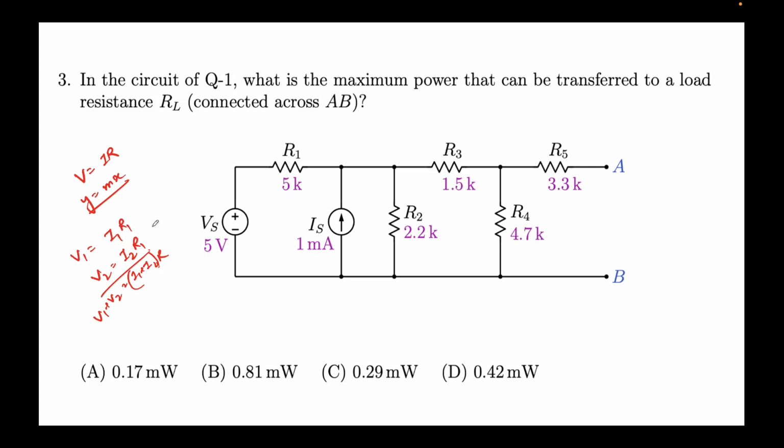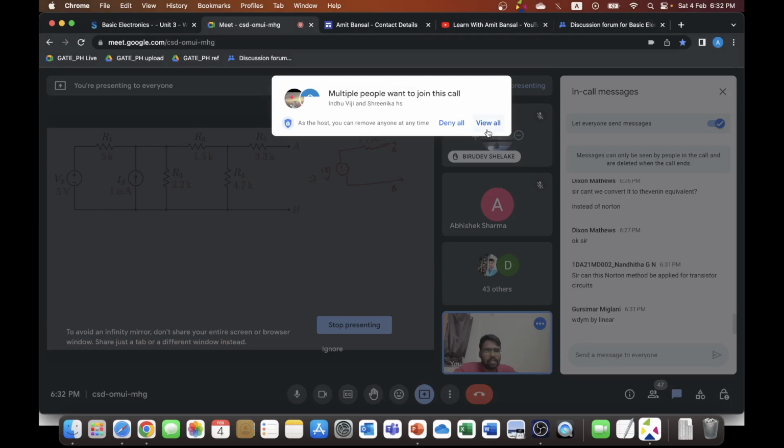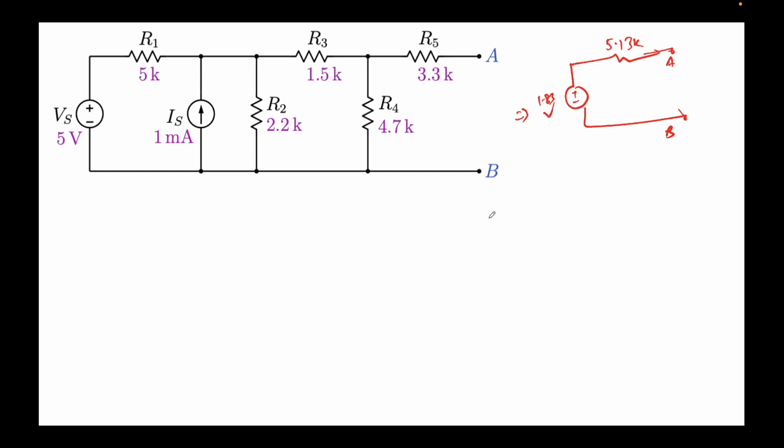Hence we are able to apply it. Transistors are not necessarily linear. There may be some regions where they are linear, but they are not always linear. So for Norton, I cannot say it will be applicable by default. We have to make sure the principle of superposition holds, and there are some other concerns. If they're satisfied, then yes, you can apply it, but it's very specific. That's what I meant to say. By the way, for linearity, Professor Mahesh Patil has explained in some depth what we mean by linearity, so I request you to revisit his lecture videos.